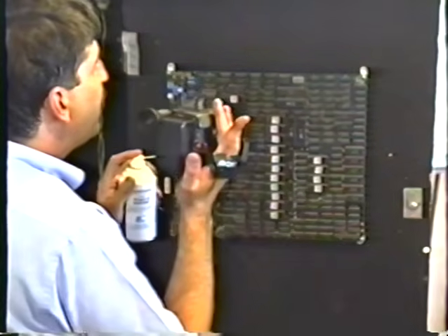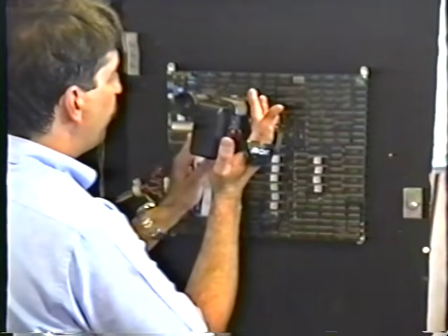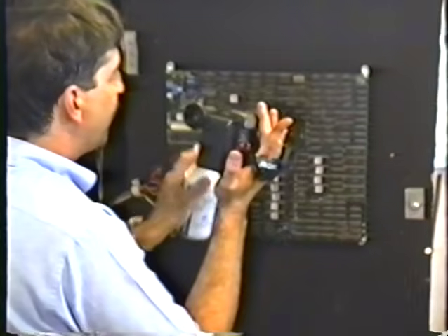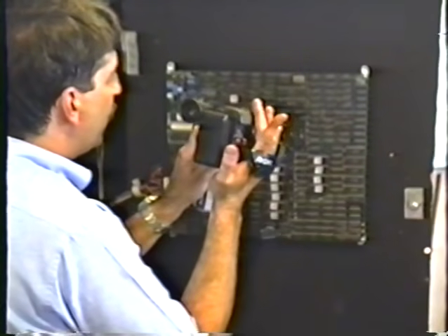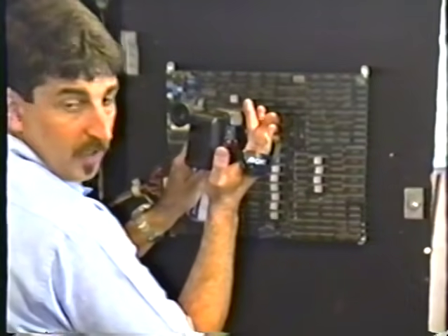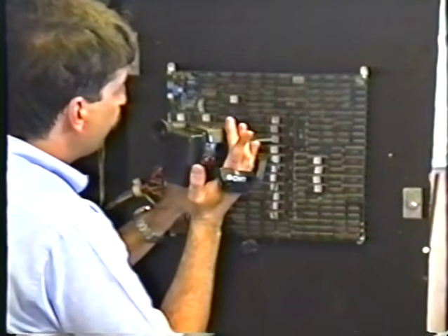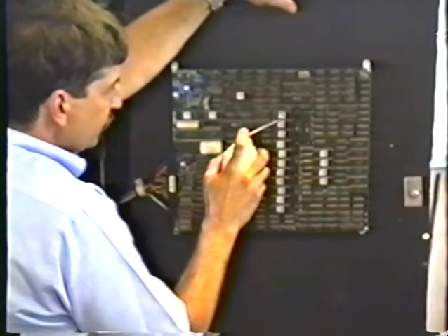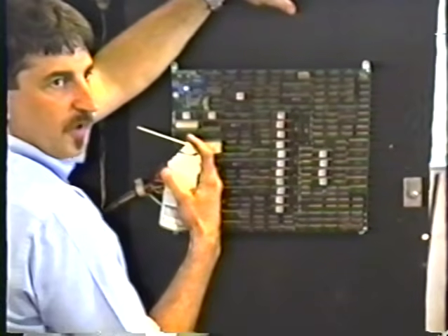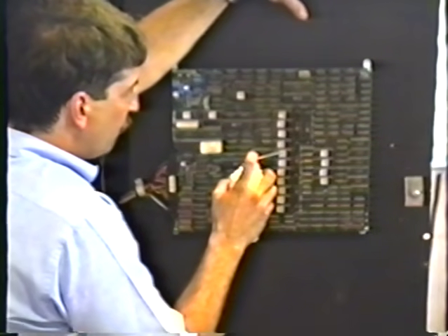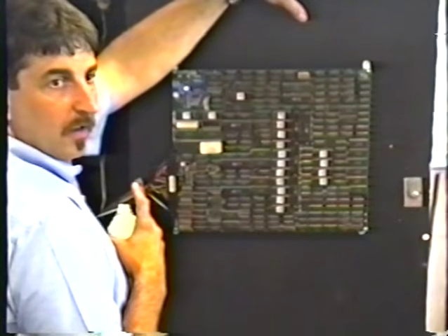one at a time you start freezing the chips. I always start with the big ICs. And you just drill, don't go like this. Just drill a little bit on it. When you get to the bad IC, the problem will go away. In other words, you hit the integrated circuit, you start hitting them one at a time. Let's see if you've got the garbage on the screen. Only occurs when it's warm. You hit it up, you freeze the chip, bingo, problem goes away.